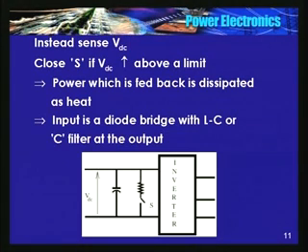So sense VDC, the moment it crosses the set value, close this, dissipate the energy in the resistor, and when it falls below a certain value, open S. Okay.